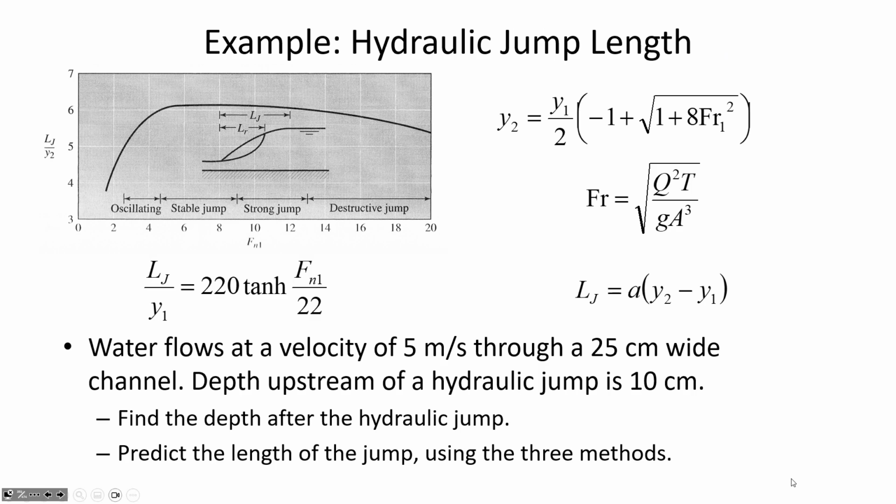All right, so that's all we'll talk about for hydraulic jumps, except for the fact that there are oftentimes hydraulic jumps that emerge downstream of underflow gates. And that's the next thing that we're talking about, underflow gates. An underflow gate could be just as simple as a piece of metal in a frame, which the metal plate is lifted, sometimes even just by hand. So a gate like this could be used in an irrigation situation where a farmer has a series of canals that irrigate water onto fields.